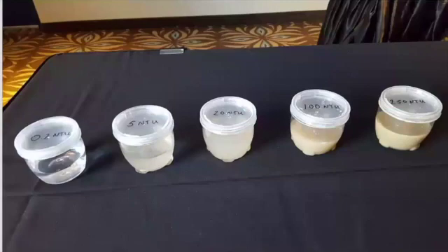In order to demonstrate what different water qualities might look like in a stream, have a look at these beakers containing different turbidities of water. From left to right, we have 2 NTU up to 250 NTU. It shows the level of sediment you can expect at these turbidities. If you estimate both the turbidity and the discharge of the receiving stream, you can very quickly, in a matter of seconds, calculate the amount of fine material being carried by the stream. From this, you can infer that upstream from this site, there is a source of sediment, the proverbial smoking gun, generating at least this amount of fine sediment.